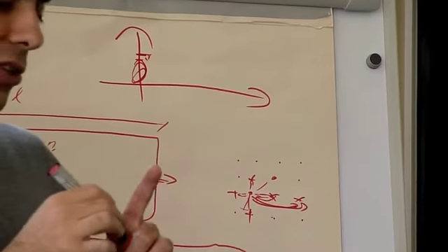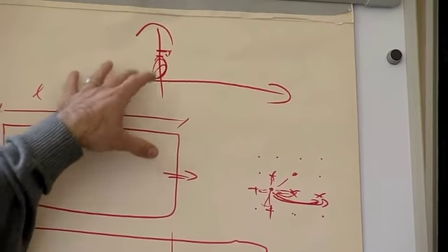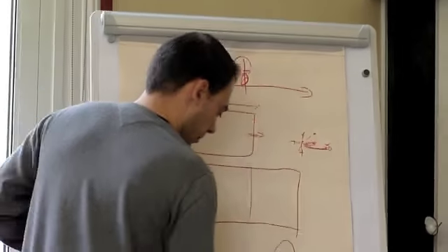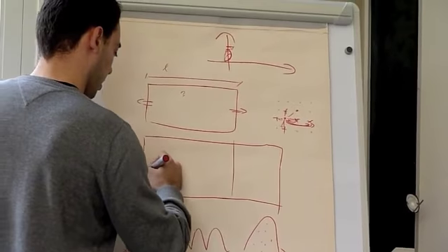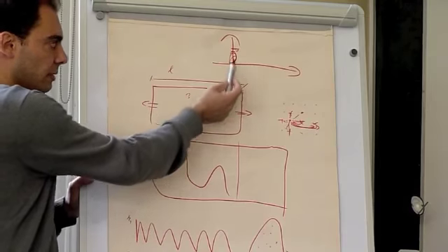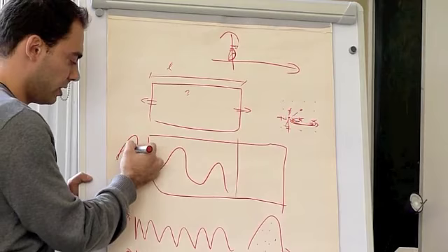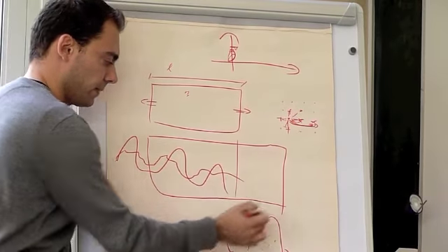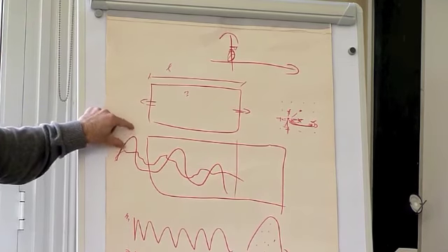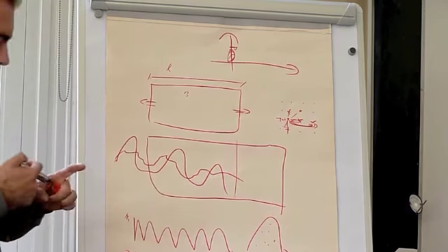The noise is basically due to random photons that add to the signal. Imagine I have a signal like this. This is the signal I want, but since there are random photons added by the amplifier, it can become something like this. Depending on how good the power of the signal is relative to the noise, it will become easy or hard for me to detect those signals.